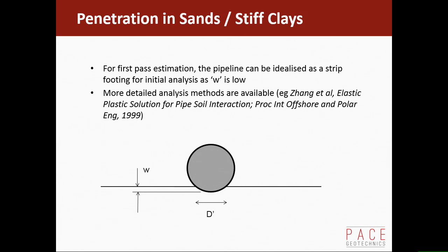You will tend to have a sand veneer, so it's not that often that you've got to consider embedment of the pipeline in soft clay or a cohesive type resistance in soft clay. Because the seabed's fairly hard relative to the weight of the pipeline, w becomes small, and it doesn't really make a big impact on the lateral stability calculations, that depth of embedment. You don't get a lot of added resistance from the embedment depth, so often a safe view is to ignore depth of embedment.